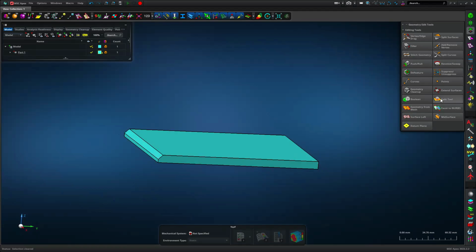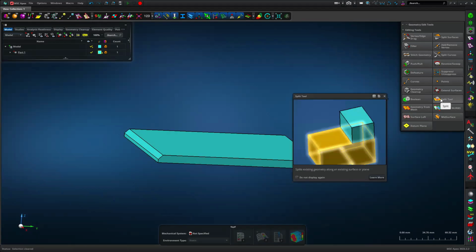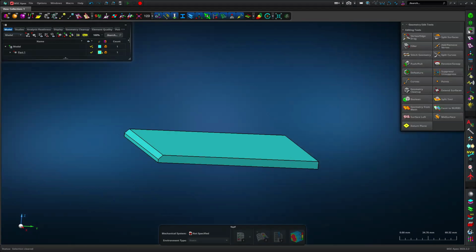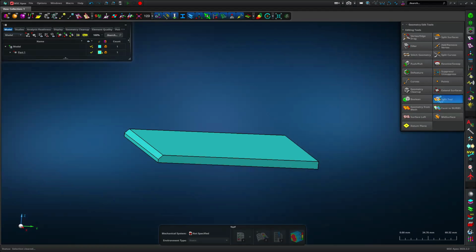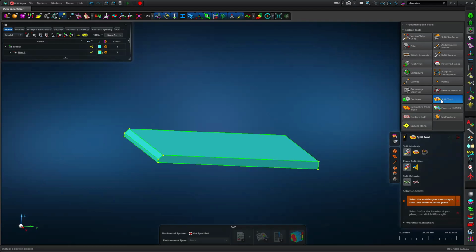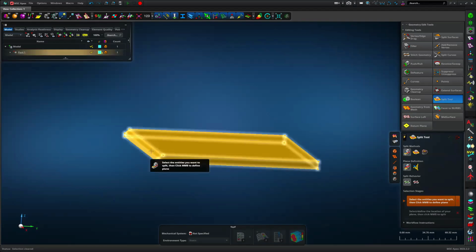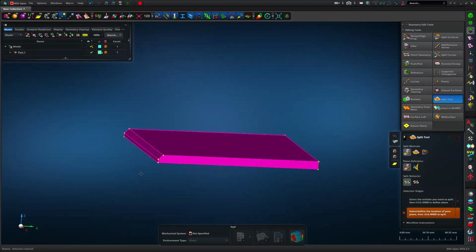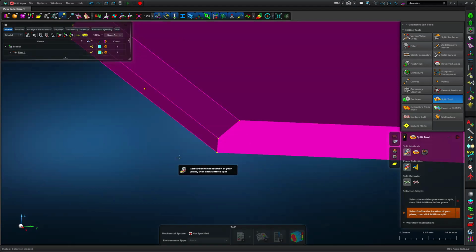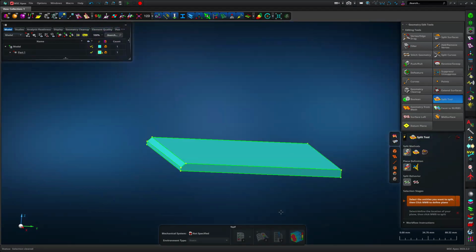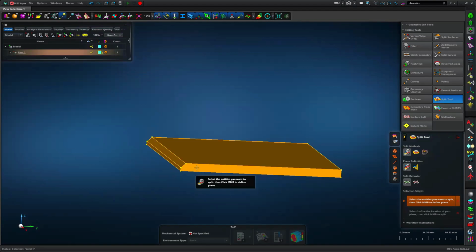Partition is called the split tool here. If you open the third green icon, there will be something called split tool. Okay, so you open the split tool. In the split tool, you can click on your geometry. Click on this particular plane. Just once again I'll repeat it: you click on this geometry, highlight it. It will be in golden color.